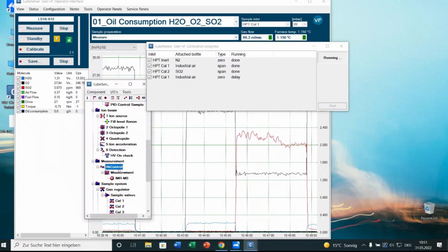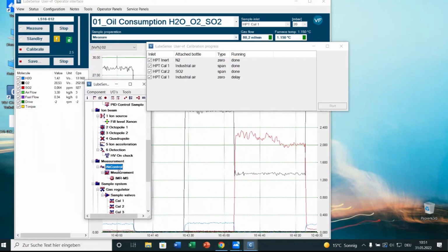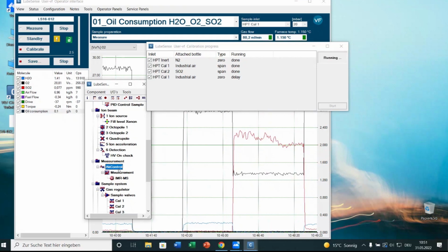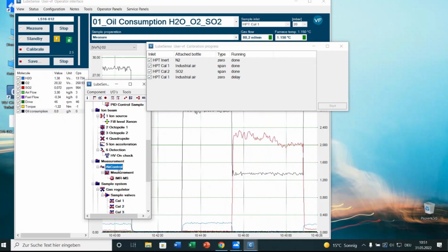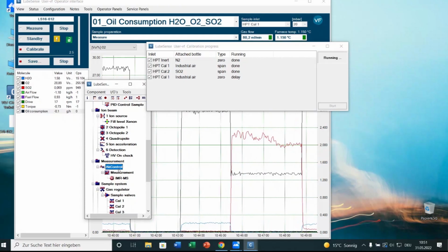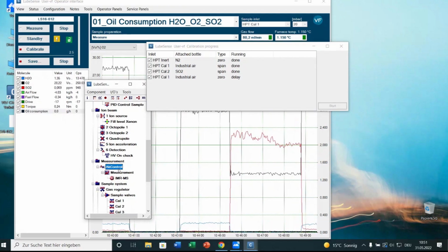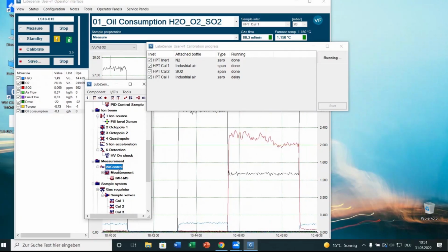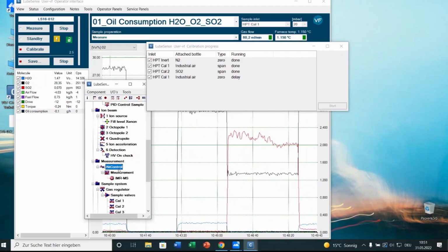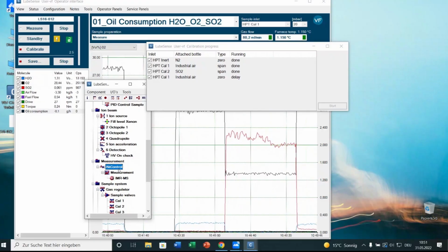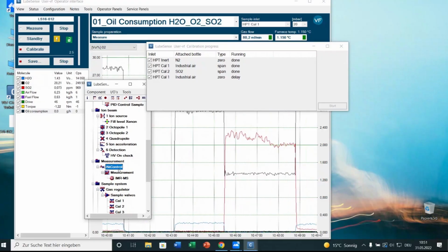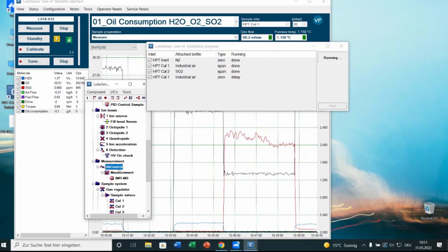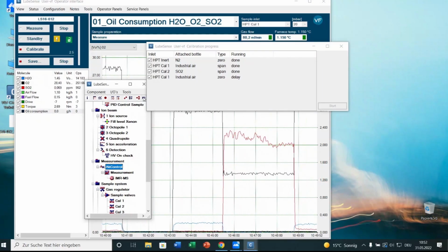I can also refer again to the auxiliary materials so that the formula can be implemented quite easily in a test bench environment. The more convenient part is that you will have the airflow and fuel flow values from the test bench available, and you only need to set the two constant parameters, sulfur in oil and sulfur in fuel. You only need to read the SO2 value from the measurement system, and then you can do the calculation on the test bench computer.